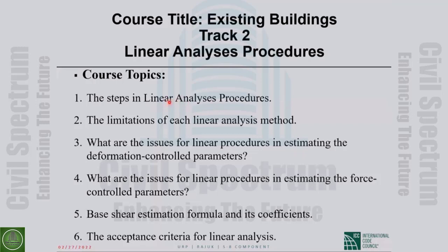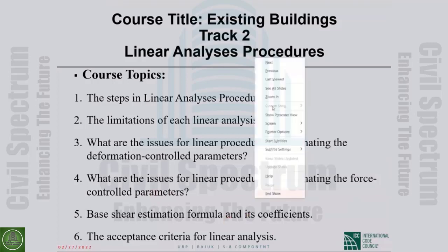And so naturally we should somehow adjust the demands that we get from the linear analysis. So we discuss what kind of adjustment we should do for the deformation control parameters, what kind of adjustment we should do for the force control parameters. So the results from the linear analysis will be a good estimation of the real inelastic behavior. So let's go and see.